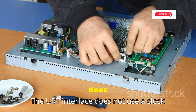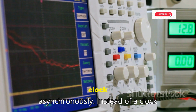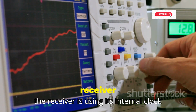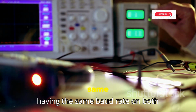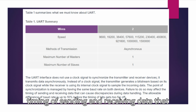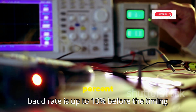The UART interface does not use a clock signal to synchronize the transmitter and receiver devices. It transmits data asynchronously. Instead of a clock signal, the transmitter generates a bit stream based on its clock signal, while the receiver is using its internal clock signal to sample the incoming data. The point of synchronization is managed by having the same baud rate on both devices. Failure to do so may affect the timing of sending and receiving data that can cause discrepancies during data handling. The allowable difference of baud rate is up to 10% before the timing of bits gets too far off.